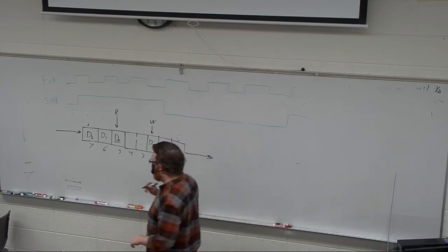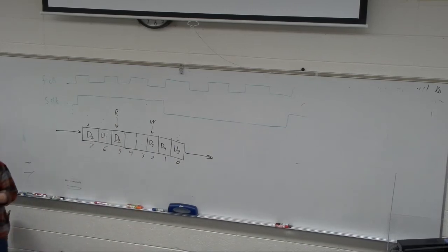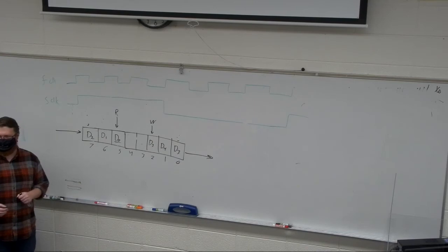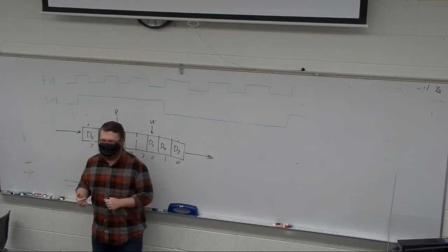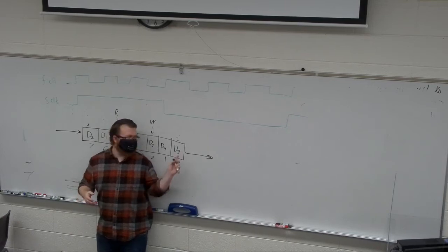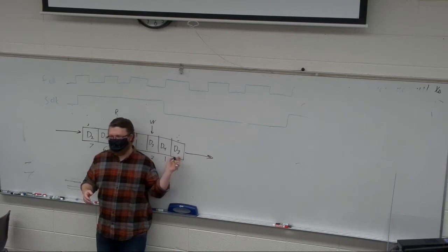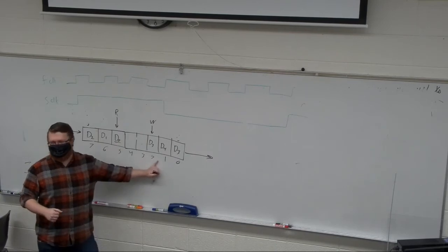Okay, so then we've had some discussion before about gray code counting, right? Where gray code is binary, except that only 1 bit ever changes at a time. Now, one thing that can be very beneficial in these types of systems to help improve stability and performance is instead of counting these indexes as binary, you count them as gray code.